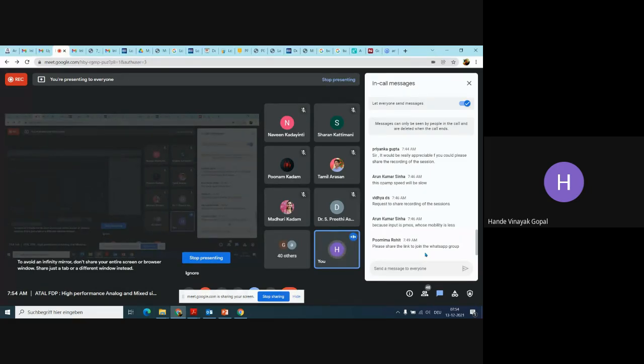It is not a large change, like 200 to 300. It may change from 200 to 250. Because of this overdrive change, you will get a lesser amount of gm than you get in a digital process. And as gm has reduced in the analog process, you get a lesser amount of gain.